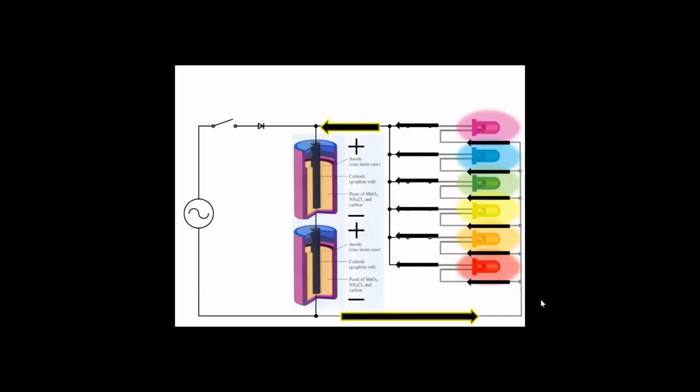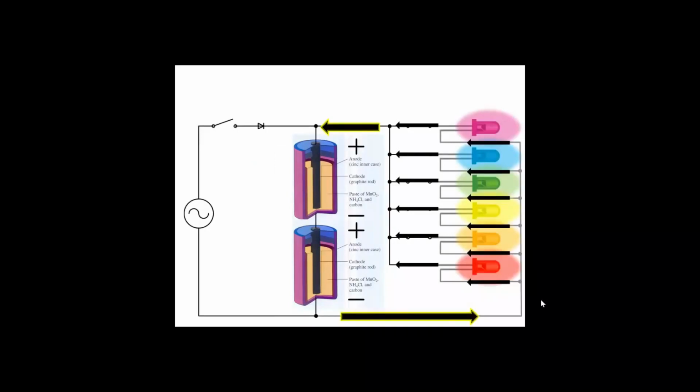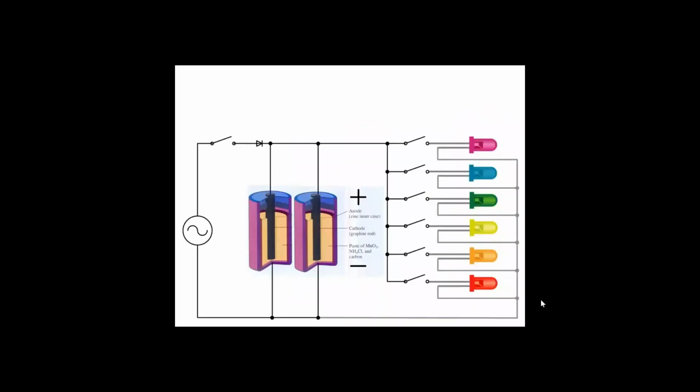2 cells in series gives us 3 volts. If we put them in parallel, we still only have 1.5 volts. If I back up here a second, this is a higher water tower, higher voltage. This is the same height water tower as one battery, but because we've got 2, that's like having a water tower that's twice as big around, but the water's still the same height over your house. So you didn't increase the height of the water column, just the total amount of water available in the reservoir to discharge down the downcomer to your house.